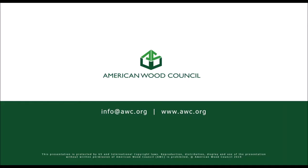Great. Thanks for that. Okay. Thanks for that background, Jason. That's really helpful. Sure. Paul, there was a question about firewalls. Can firewalls be used in these new types of construction to increase building areas like we do currently in other types of construction? Yes, if it's a true firewall, which for buildings of this height is going to be difficult to accomplish. But yeah, as for any other type of construction, you can use firewalls to create a new building on the other side of the firewall. Great. Yep. Okay, super.